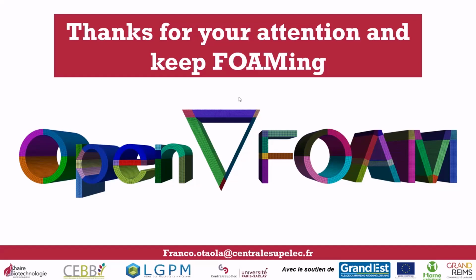Final question on my side. The FDI geometry, the block cone: can you share that geometry just to test it, or did you run the actual simulation using that mesh? No, for the moment, no, because I developed it during my holidays and I didn't have a computer to test it with. But I already ran checkMesh on the geometries, and they are really good meshes in terms of quality. Obviously, they don't have boundary layers.